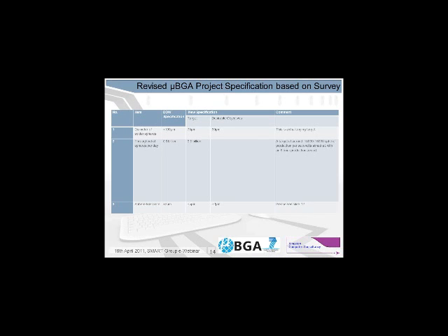The first thing was the original diameter of solder sphere that we were aiming at, probably 2 years ago when the project was first proposed, was 100 microns. Our new target is 75 microns, and we're hoping to get down to 50 microns. As you can imagine, this is a fairly challenging target.